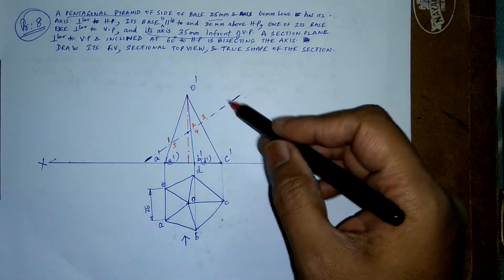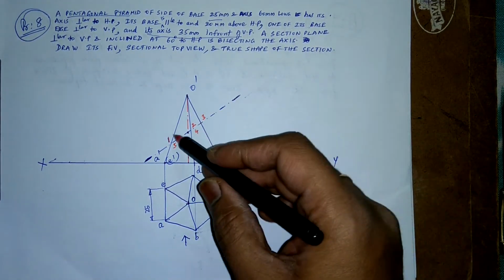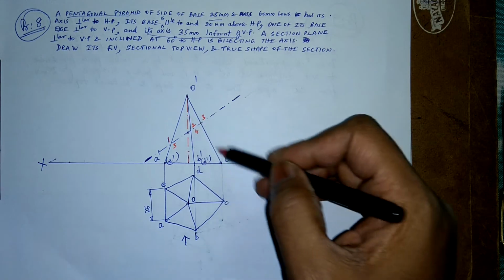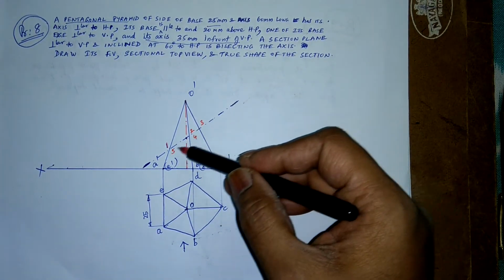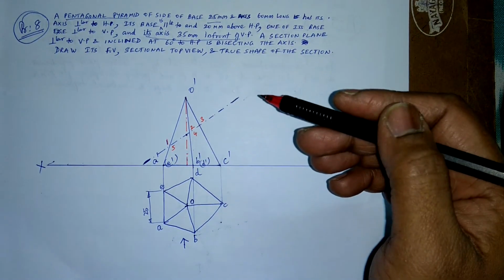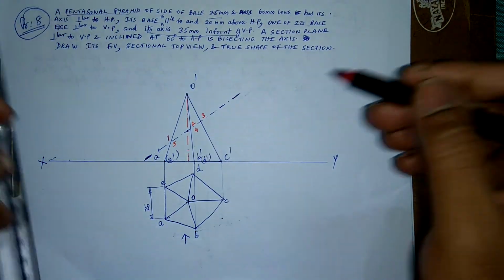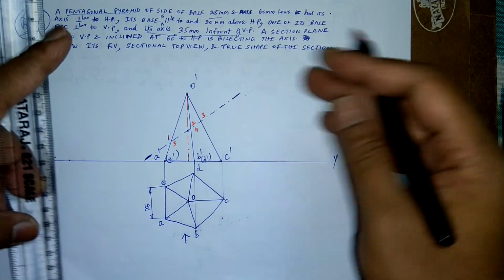Totally on the lateral surface I have so many edges being cut. These are called the slant edges. Right. So slant edges are cut here. So I have 5 points over here. Alright, this is my front view, where I numbered the points.